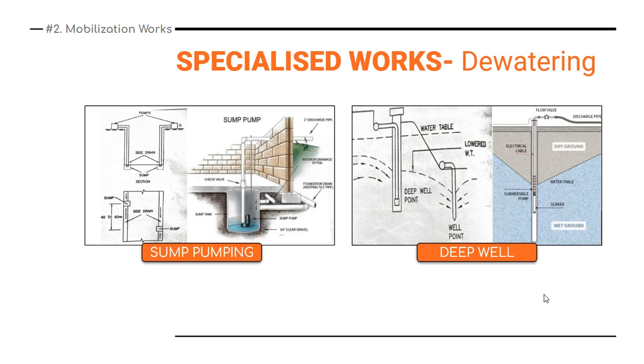Okay, but in case of deep well dewatering, what happens is you need to engage a lot of centrifugal pumps. You need to first have certain borewells out there, at least for 1000 square feet of land area you need to have at least 30 to 40 centrifugal borewell areas, where the deep point is kept and where the water is drawn out, and again it is thrown out in a very distant place.